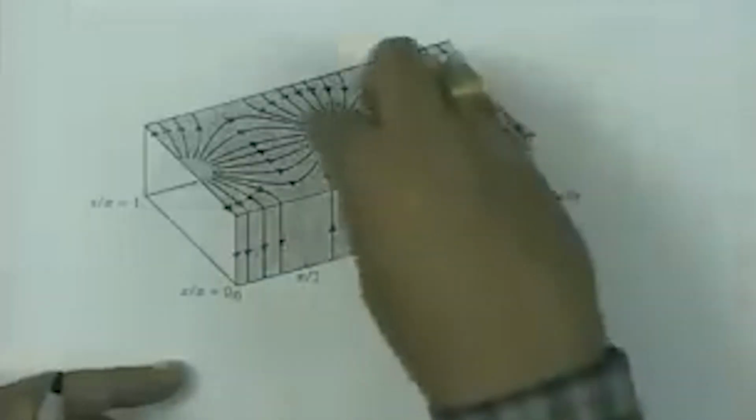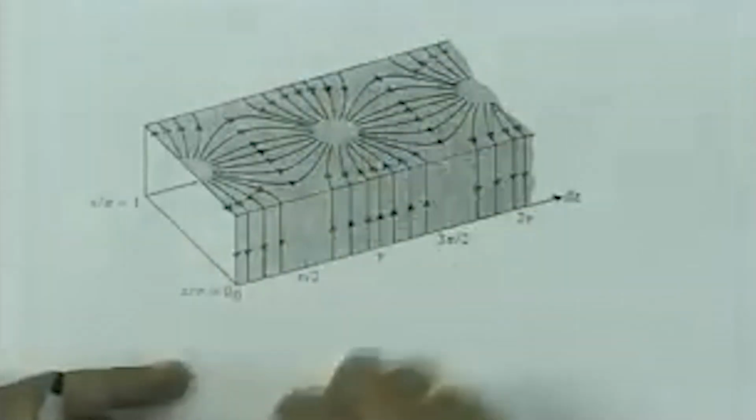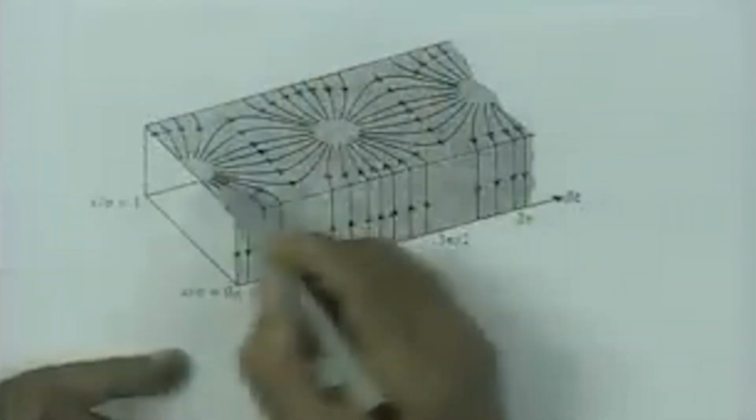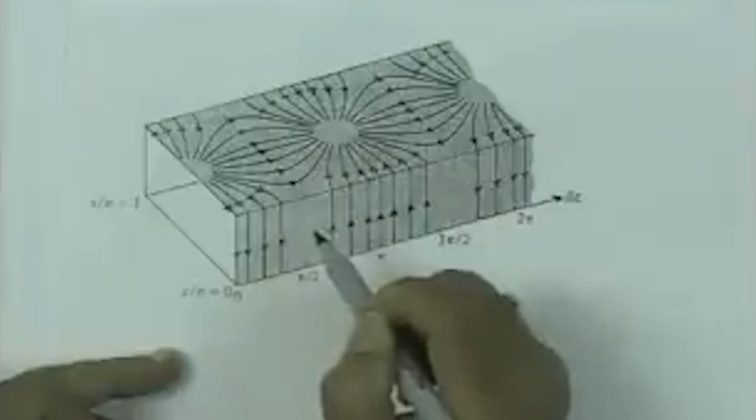So that means there is an accumulation of charges which take place on the 2 walls, and the charges keep going back and forth, and essentially the current flows on the surface of this waveguide. Same thing essentially is going to happen here also, that every lambda g by 2 you will have a current island kind of created.